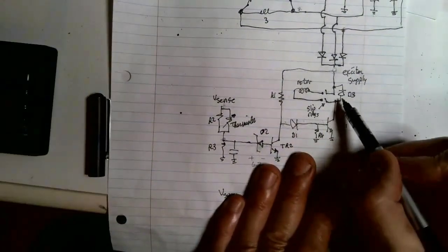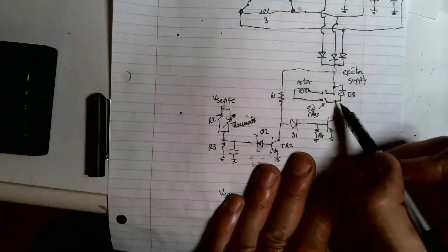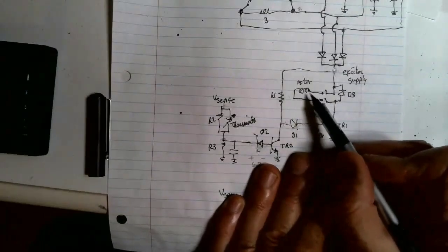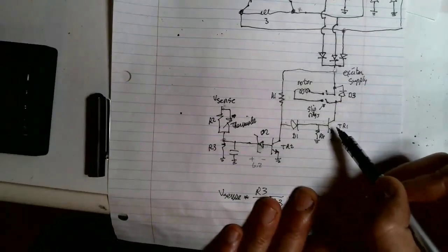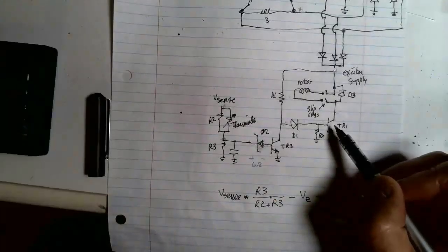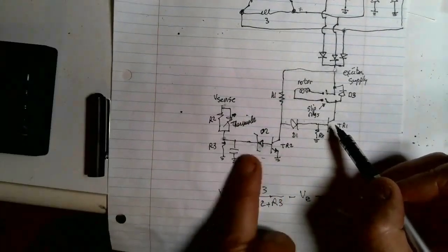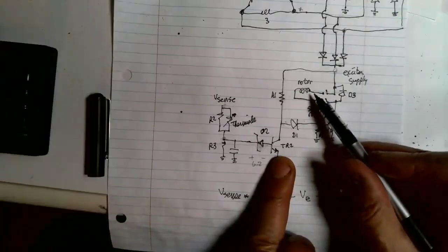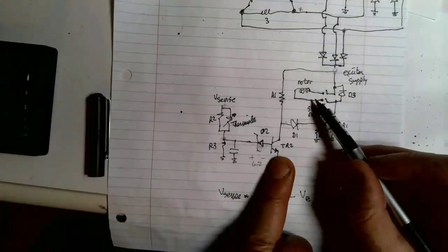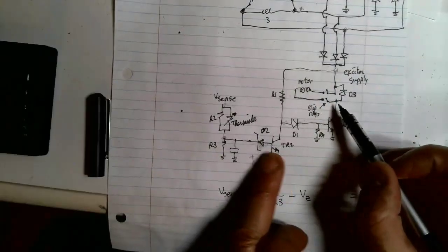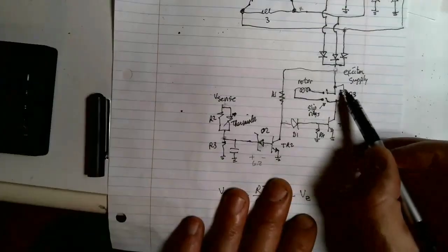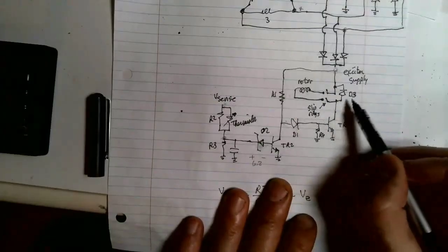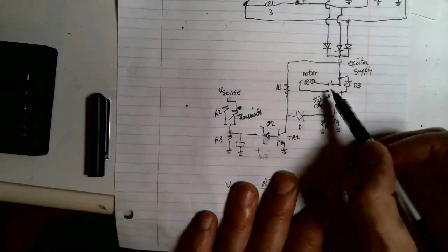Okay, one last diode I wanted to point out. Here is one of those, I think they call them flywheel diodes. You notice it's right across the slip rings which feed the rotor. This diode is there for protection. It protects this transistor. If some transient happens over here on the sense line, for instance, and this alternator tries to shut off the rotor current real quick, now, this rotor is a pretty big inductor, and if you try to shut off its current, it's going to give you back a huge transient. So this is a diode that allows the rotor current to continue to flow so it doesn't destroy this device.